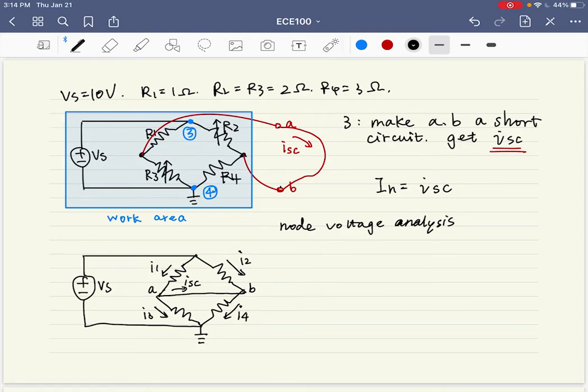That is a tricky trap. Let's just keep A and B separate and use the negative polarity of the voltage source as the reference node. This is V1, node 1. This is node A. This is node B, right? For V1, we directly get its value, so we don't need to write the KCL equation for it. And for node A, the current flowing in equals the current flowing out, right? Let's substitute the current variables with our node voltages.